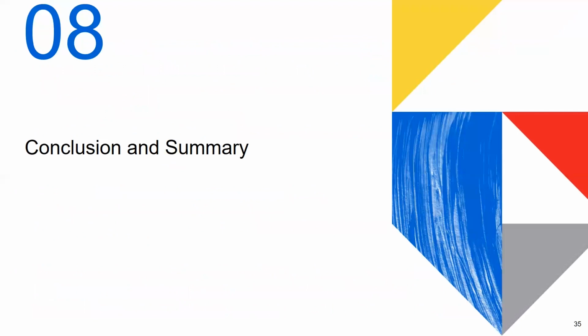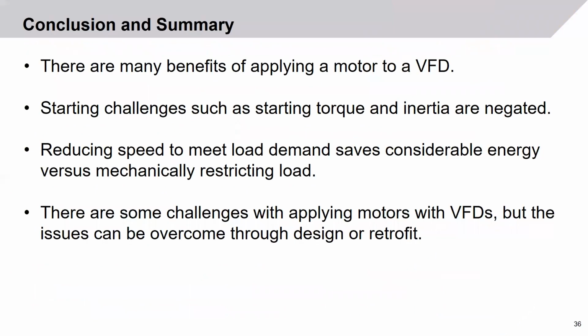So conclusion and summary. There are many benefits of applying a motor to a VFD. Starting challenges such as starting torques and high inertias can be negated. Reducing speeds to meet a load demand saves considerable energy versus mechanically restricting the load. There are some challenges with applying motors with VFDs. However, those challenges can be overcome through design and or a retrofit.